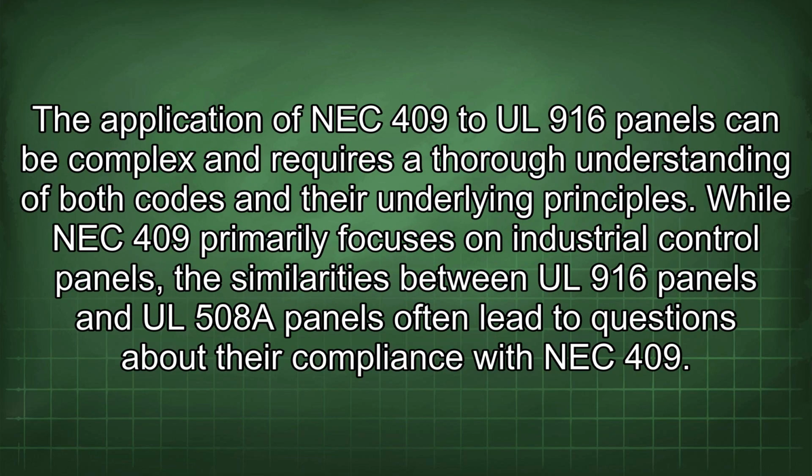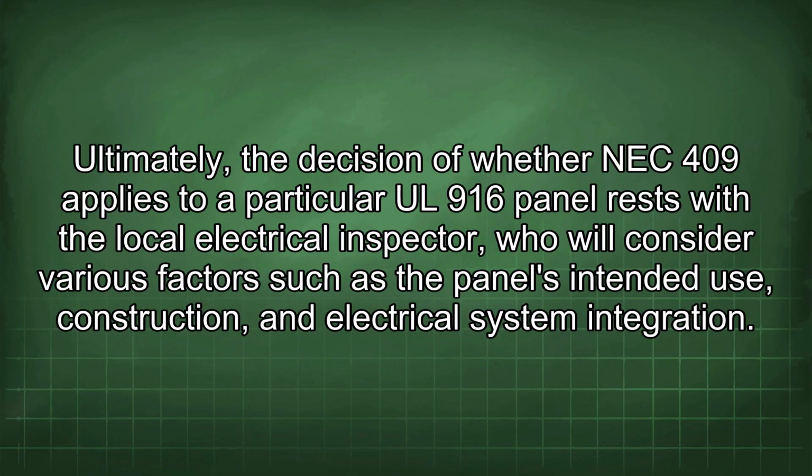The application of NEC 409 to UL 916 panels can be complex and requires a thorough understanding of both codes and their underlying principles. While NEC 409 primarily focuses on industrial control panels, the similarities between UL 916 panels and UL 508 panels often lead to questions about their compliance with NEC 409. Ultimately, the decision of whether NEC 409 applies to a particular UL 916 panel rests with the local electrical inspector.